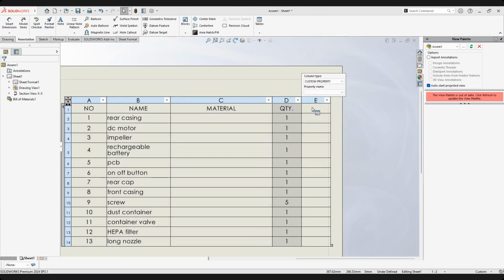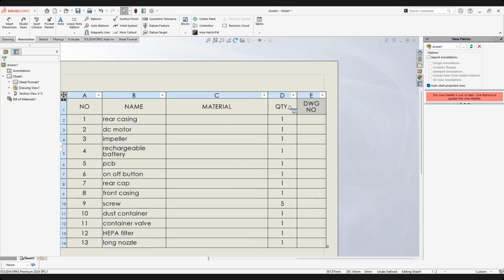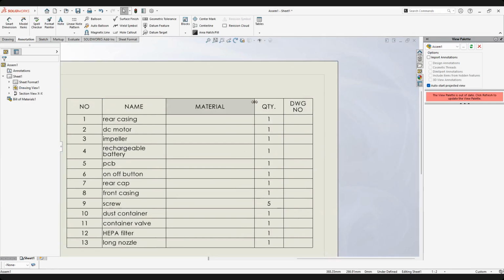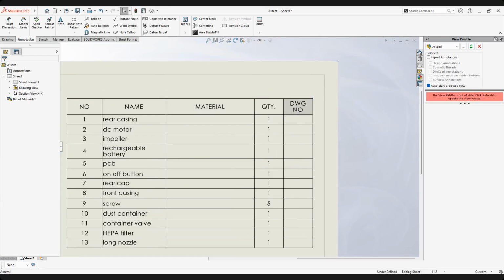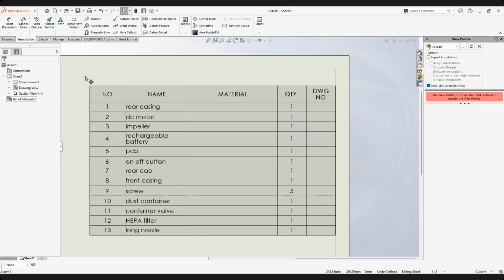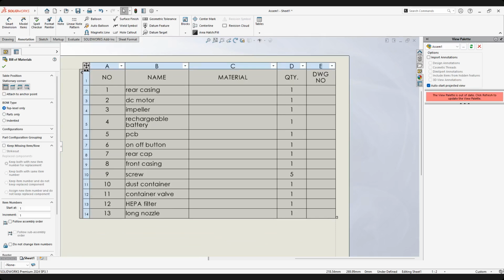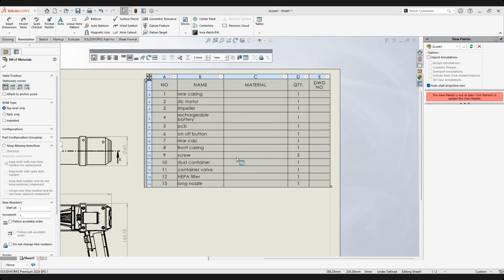This one here, another new column here is about drawing number, right? What is your drawing number? So you do it like this, right? Drawing number. Okay, here I can, so I have space. All right, drawing number. So now I drag your, hold on. Drag that to snap at this. It cannot be floating, it must snap at that borderline. All right. Okay, drawing number. Later you will complete everything here. Everything must be in capital letter.